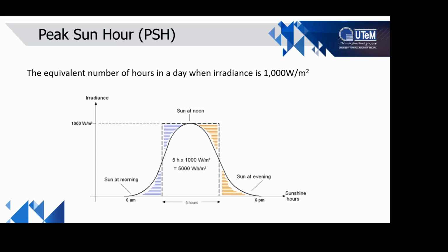Okay, so when we talk about the shape or the DC-AC ratio, we refer to the bell curve here. Basically, if we set a higher amount of PV capacity, we are going to lose part of the energy at the top here.